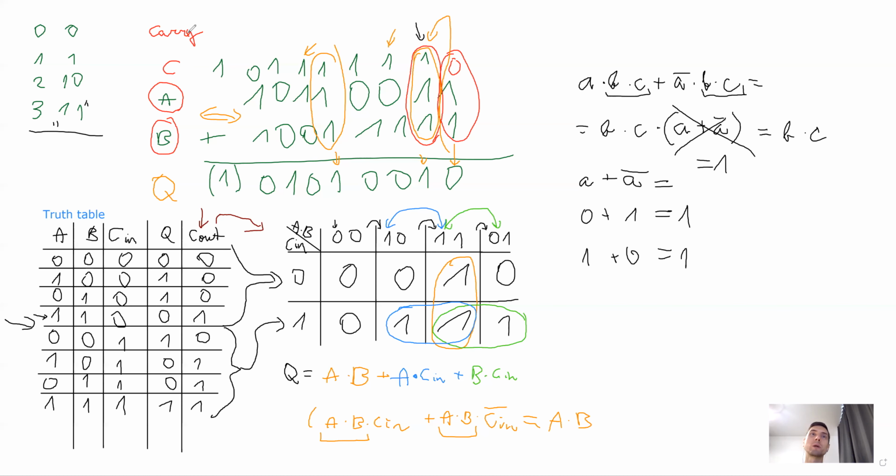Okay, so this is what we got. I will delete this thing. And in black, I will do the second part, which is this. Here it's also explicitly visible: here is AND-OR. We want to use only NANDs and NORs and NOTs. So I write double inversion on top, and I'm going to break the line here and here. So it will be A, with the colors, A times B inverted, so it will be A NAND B plus